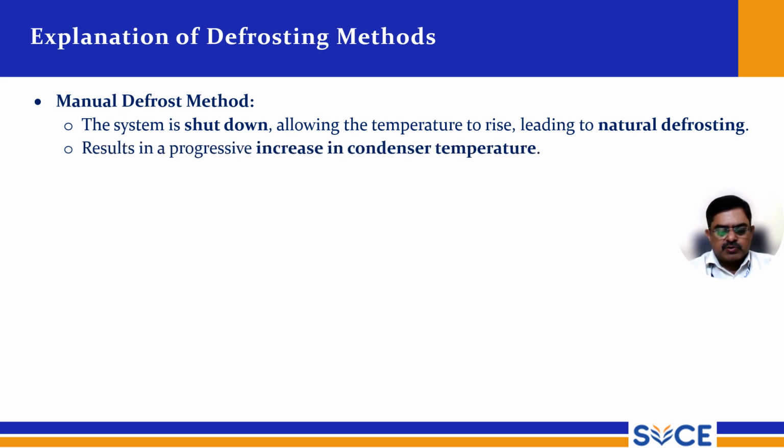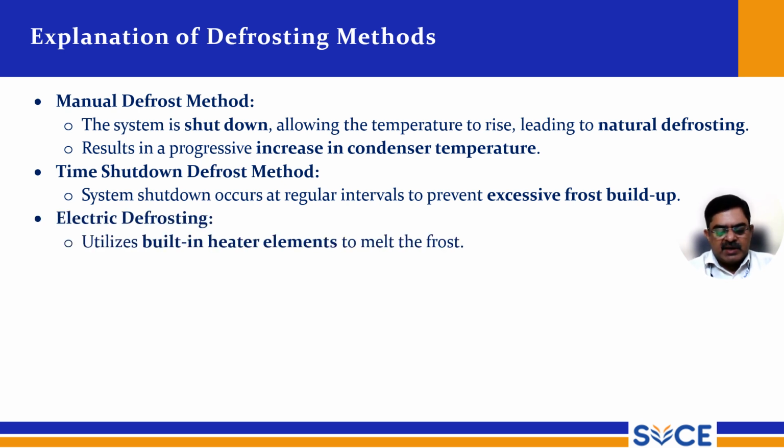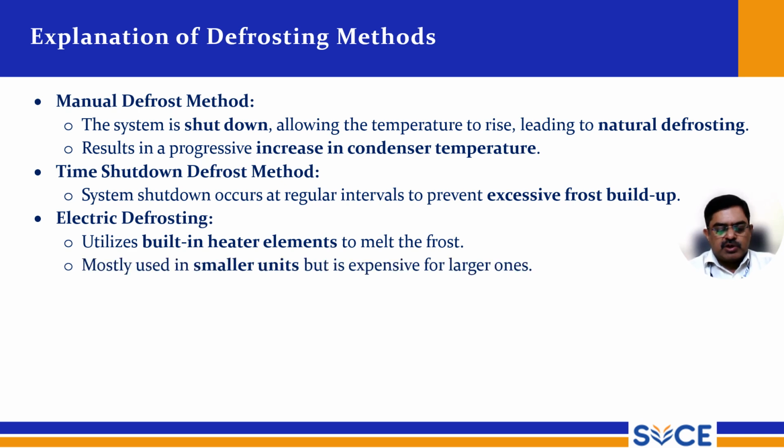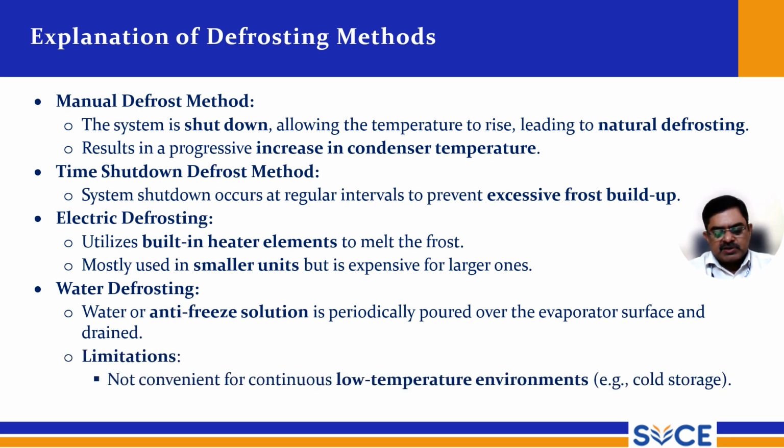In the time shutdown defrost method, system shutdown occurs at regular intervals to prevent excessive frost buildup. Electric defrosting utilizes built-in heater elements to melt the frost, and is mostly used in smaller units but is expensive for larger ones. In water defrosting, water or an anti-freezing solution is periodically poured over the evaporator surface and drained. The limitation is that it is not convenient for continuous low temperature environments, so it is not much used and not suggested.